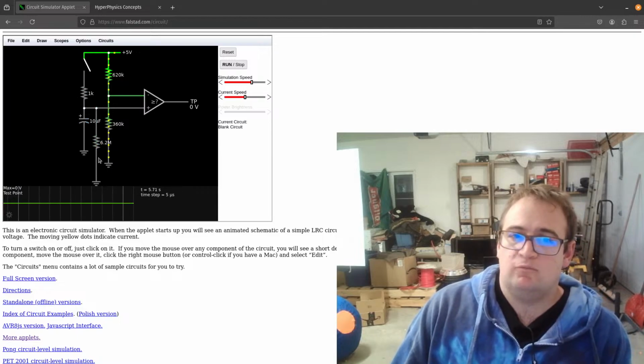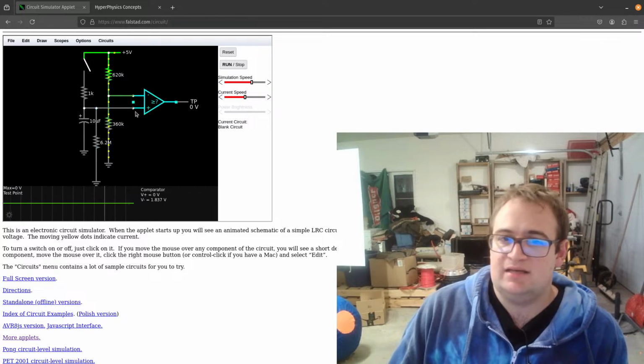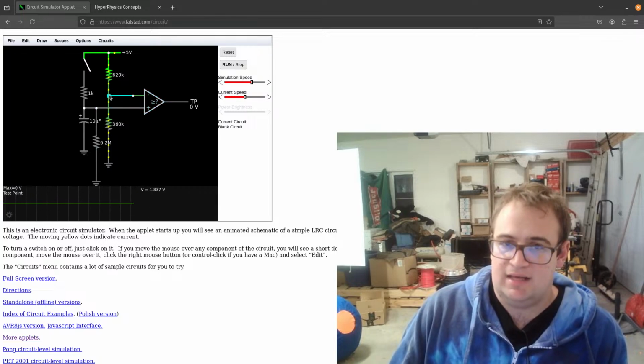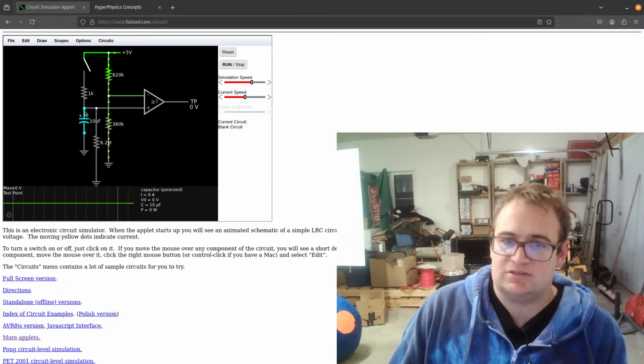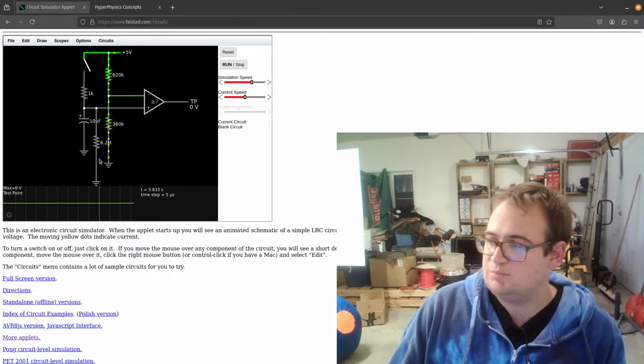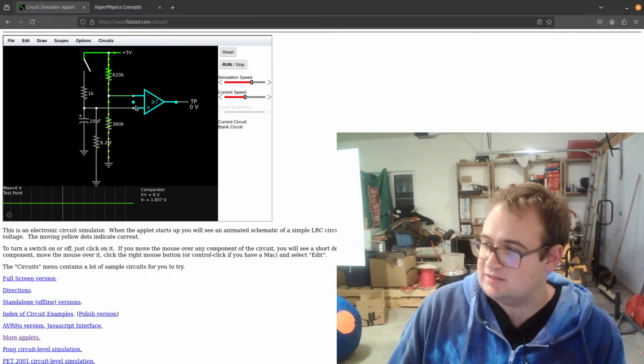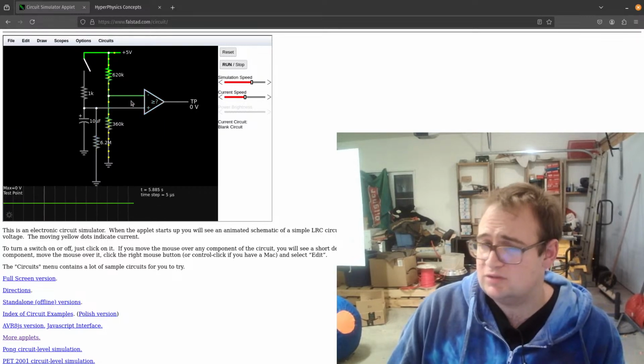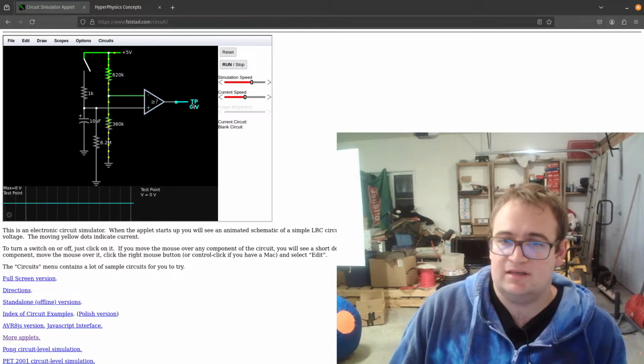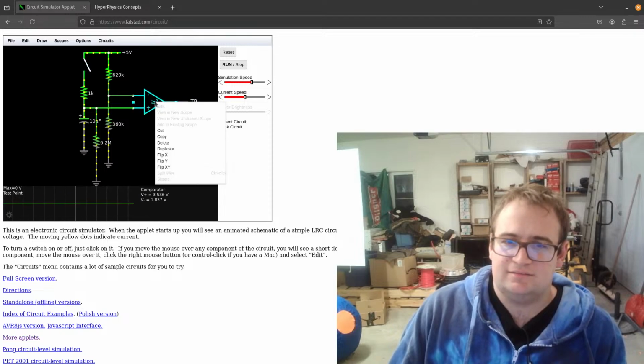And then this is going to go higher than this, which will make this output high. And then this will slowly discharge through this 6.2 megaohm resistor, and when it discharges below 1.8 volts, this will go low again. So let's see if that happens. It doesn't.